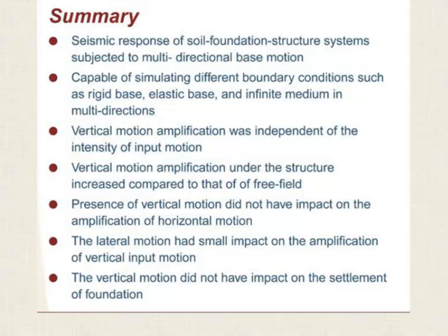The presence of vertical motion did not have impact on the amplification of horizontal motion, and the lateral motion had small impact on the amplification of vertical input motion. And lastly, the vertical motion did not have impact on settlement of foundation for frequencies that are far from resonance.